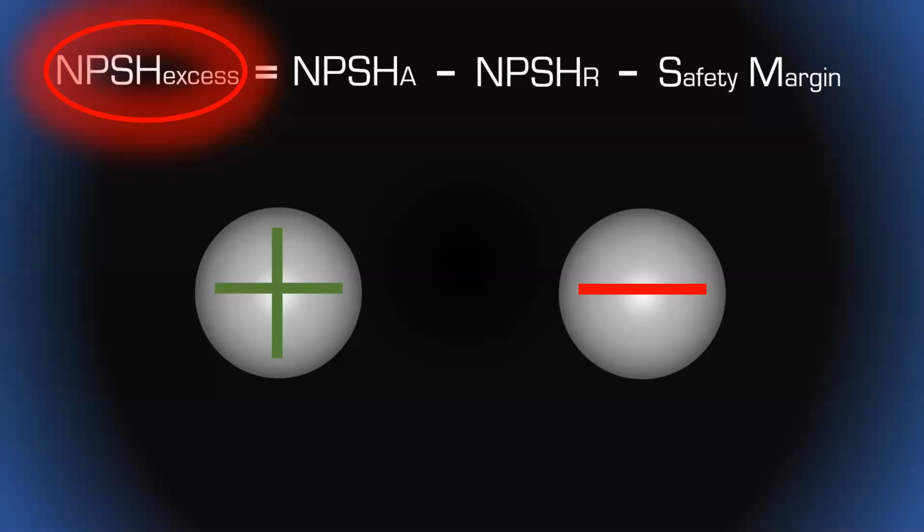Very good question. Well, the pump is going to have a flange, and at that flange, and then inside that flange towards the pump, that's all been taken care of. So if, let's say, you have a reducer or increaser coming into the pump, then you definitely have to take that into consideration. But after that flange, you shouldn't have to take anything else into consideration between the flange and the impeller. So no exits, or entrance, I guess, exit or entrance. That's all been taken into account in the NPSH-R of the pump. I hope that answered the question.